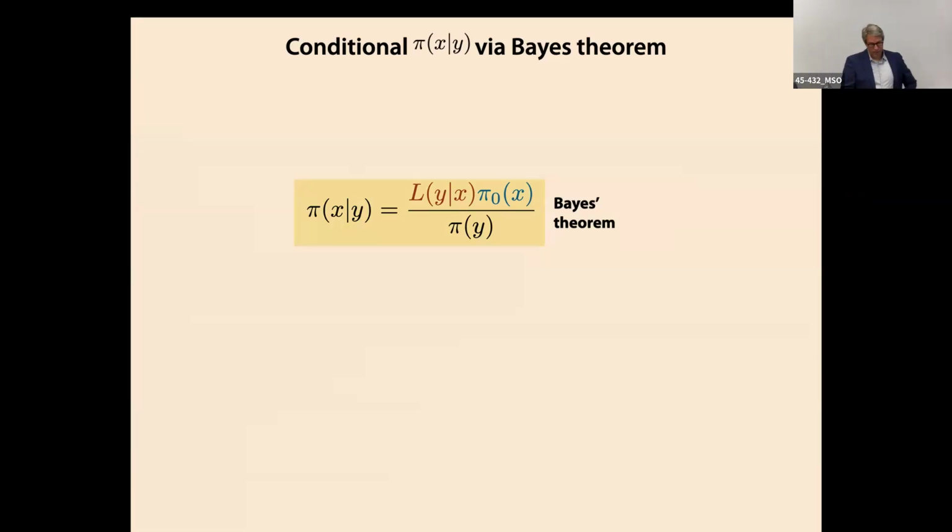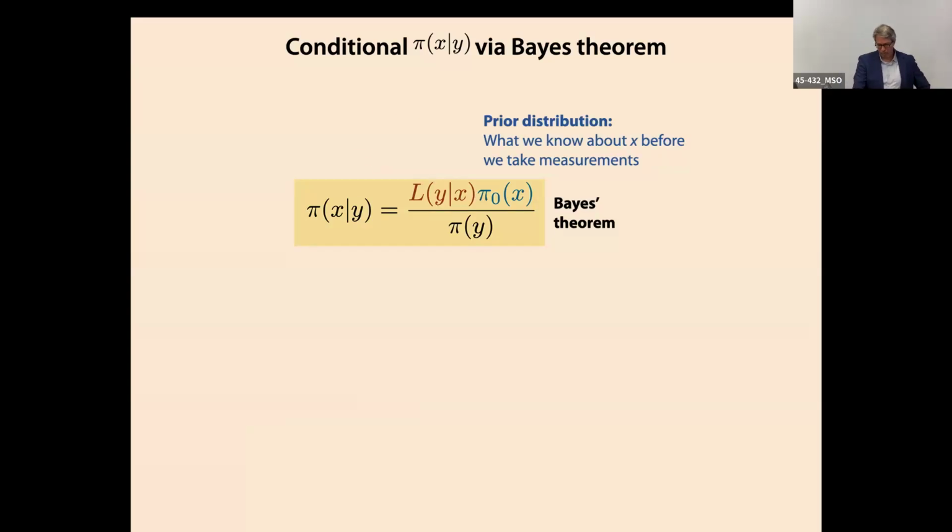Bayes' theorem is a very principled way of getting at this conditional probability, because I can start with some prior distribution that I know from prior knowledge, okay? Some idea about what my probable states are. And then I just march this through Bayes' theorem with a likelihood. This likelihood is much more sympathetic to what we have available to us, because it's the reverse of things, right? It says, if I know the flow state, what are my likely measurements, okay? And that's something I do know, right? So that's the sort of forward observation model that I showed you before. If I know the flow state, I can tell you very precisely what I predict my measurements to be.